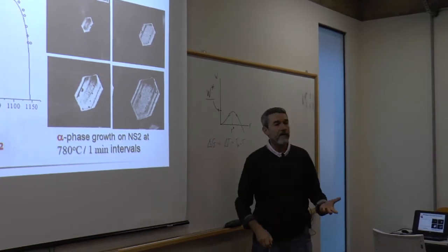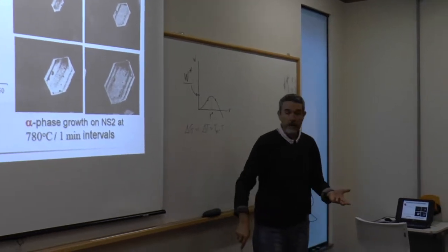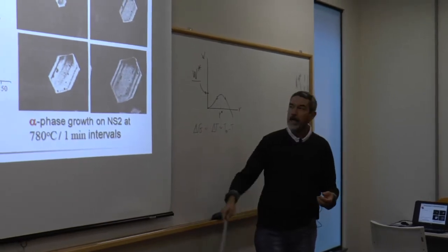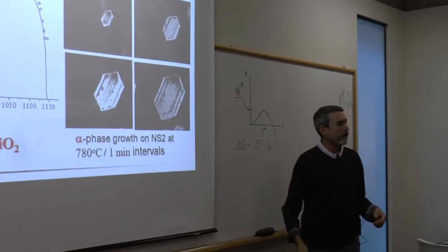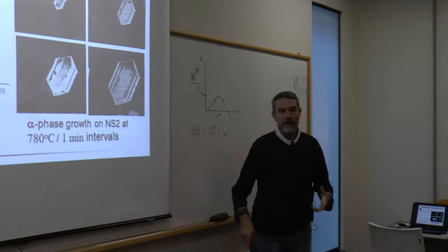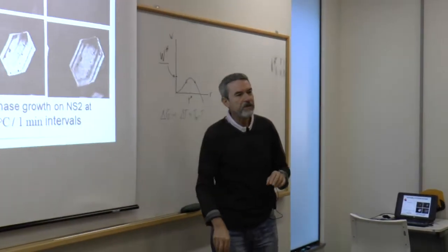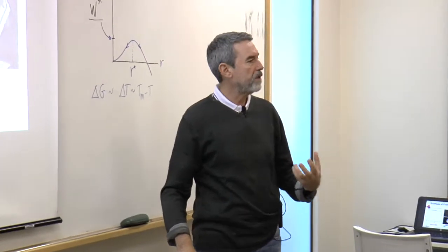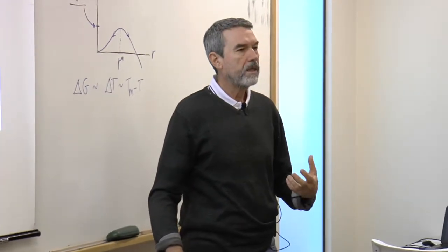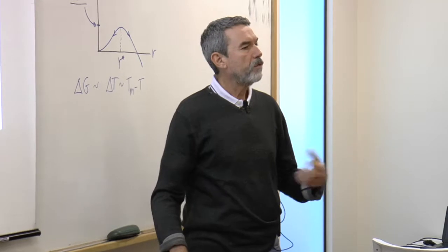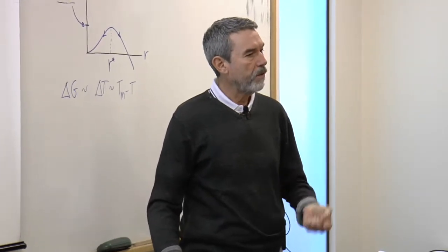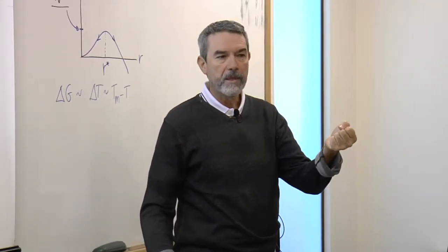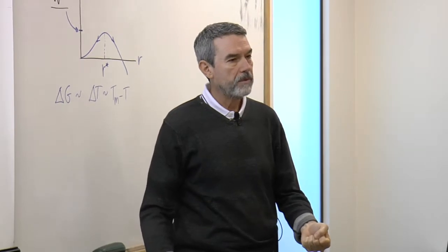If you don't have a heating stage microscope, you can also heat treat a sample for, say, 1 hour, quench the glass, and that's a nice feature of glasses. They're so viscous that they're good model systems to understand crystal nucleation and crystal growth features. You heat treat the glass, and you quench that sample.